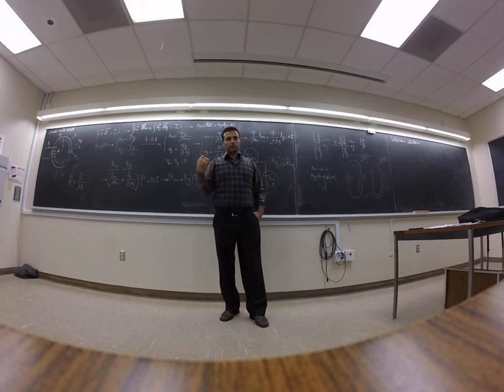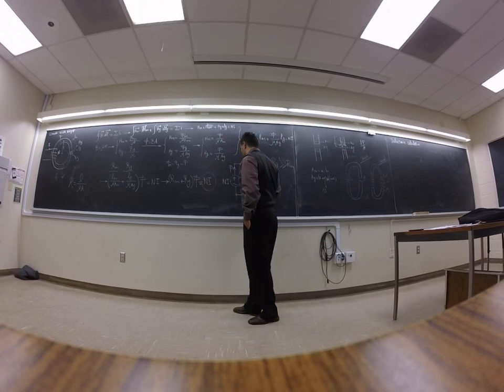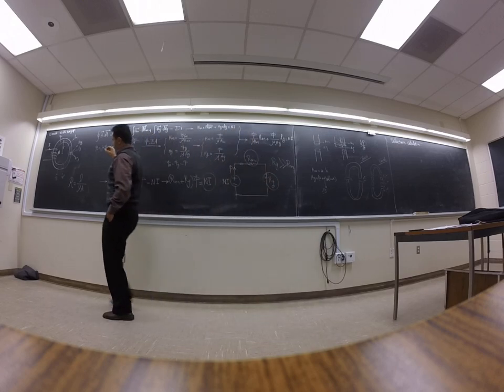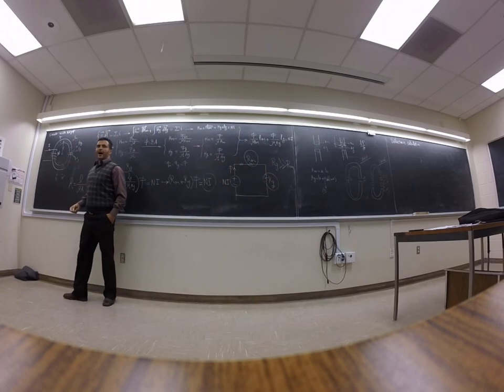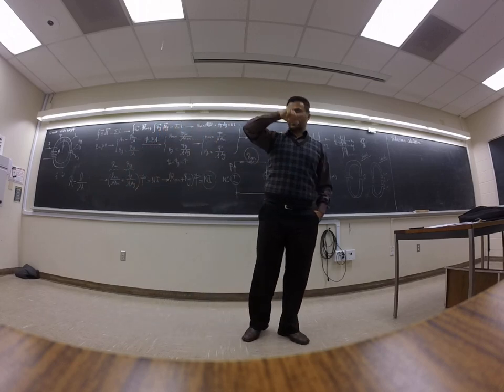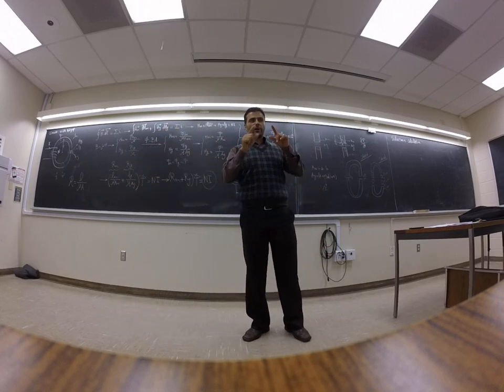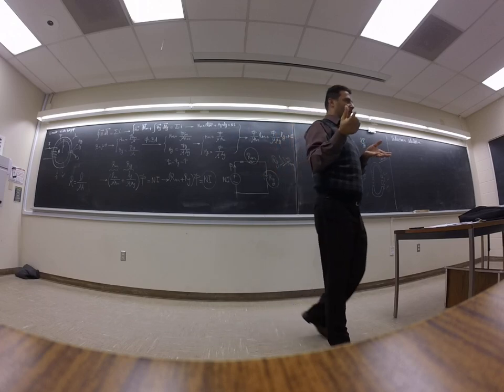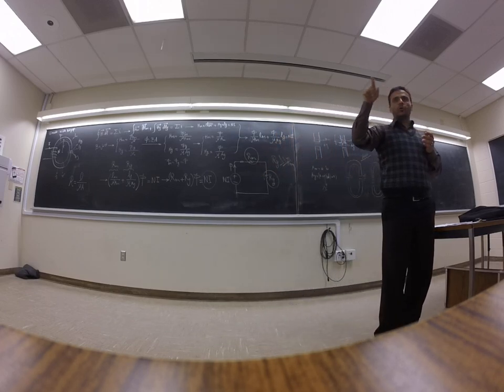Before moving to this part, I said the air gap is the way you usually control the flux. Now, new materials are usually like a donut. Most of them are like a donut. There are two types of core. They are like an EI core, which you have seen in regular transformers, and they have donut cores usually. There is no air gap.